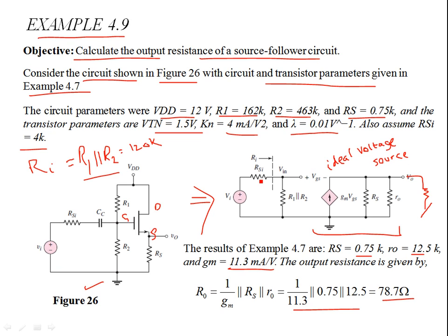Because the input resistance Ri is large compared to RSi, there's minimum loading, and Vπ is approximately 98 or 99% of Vi, so it's approximately Vi. The loading effect due to R1 and R2 is there, but it's small. If R1 and R2 are much greater than RSi, the input is present at the gate as it is.